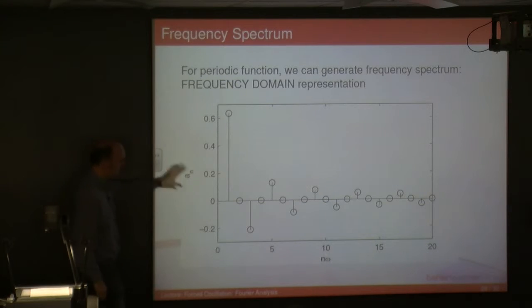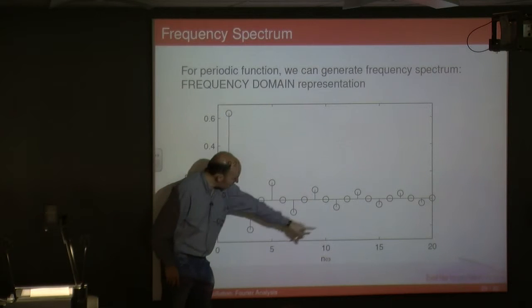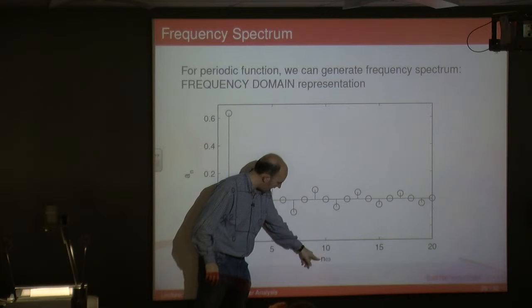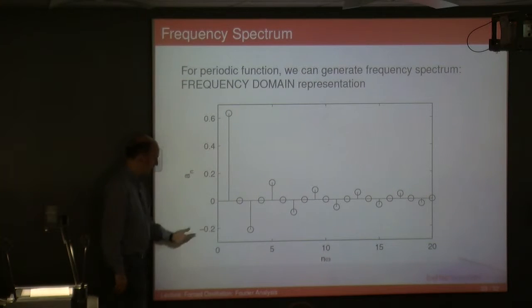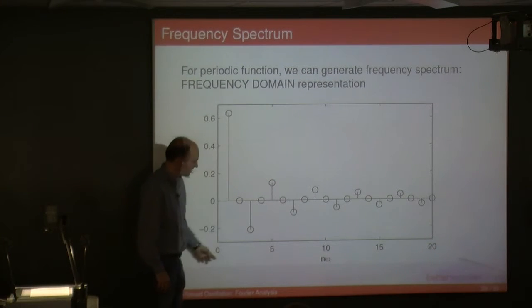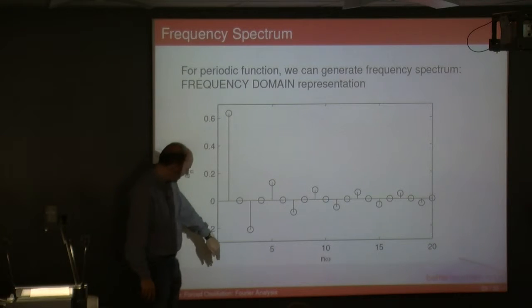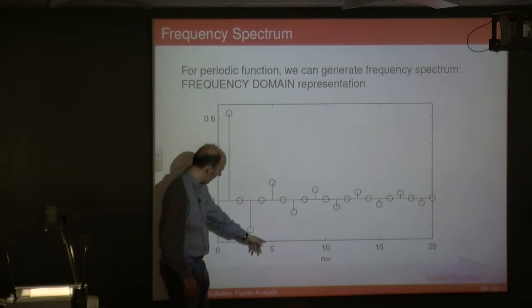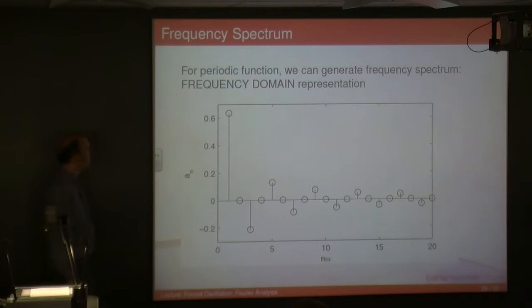And this is known as the frequency spectrum. It's in terms of frequency along the bottom. This is slightly incorrect because obviously this value here is n, not n omega. Omega is the fundamental frequency, so this should actually just be n along the bottom. But obviously I could write omega 1, omega 3, omega 5 and so on if I wanted to actually give you those values at that point there. So that's the frequency spectrum. It's frequency on the bottom, and then the strength of that frequency that's playing a part in putting together your function. This is what's known as a frequency domain response.